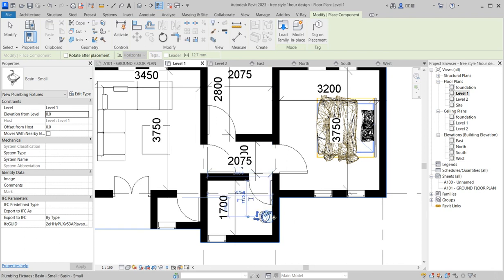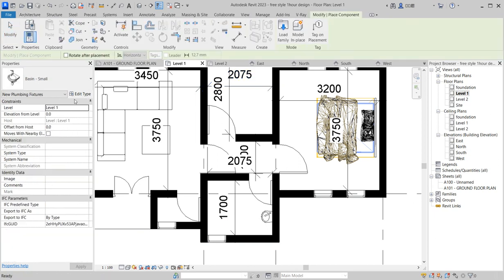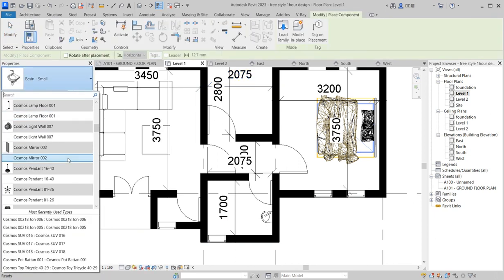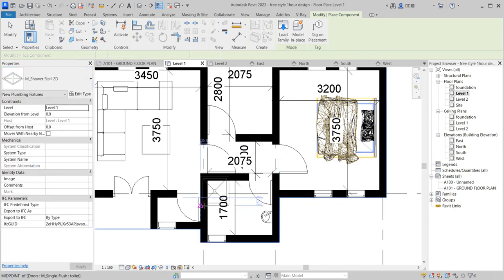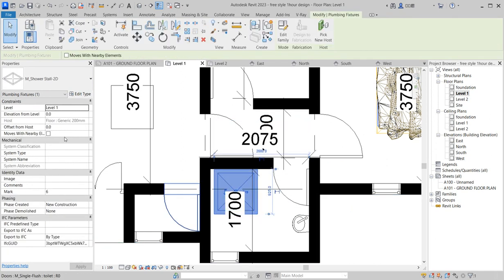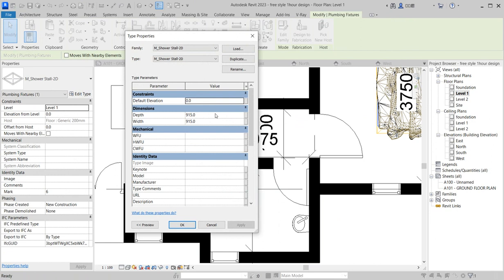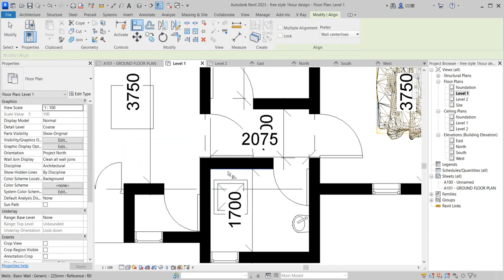So we're wasting time on things that are not too much important, but these are important because in an elementary design, when you do that, then you select the WC or you select this shower tray, you put it here. Now you can edit this shower tray. So click here and say edit type. So edit this particular one. So I'm changing to 700 by 700 because I don't see anybody that can be of a bigger size than that. So I have this like that and say align to the wall, align to sideways.